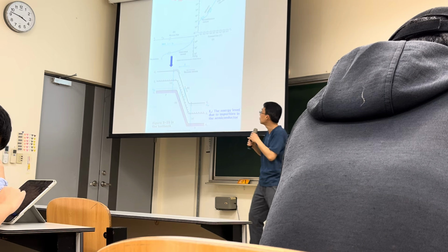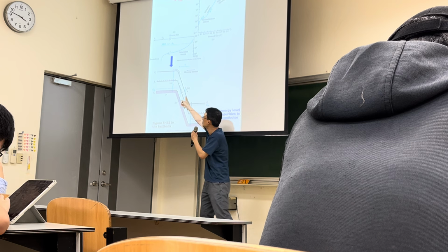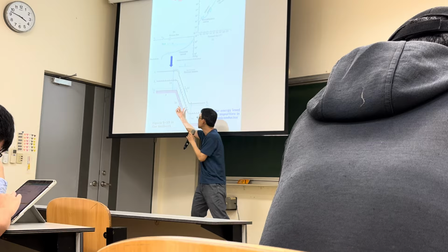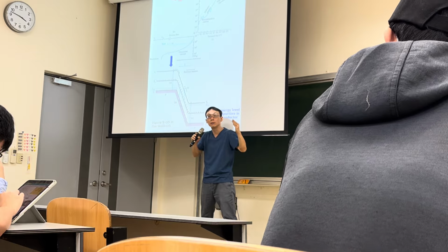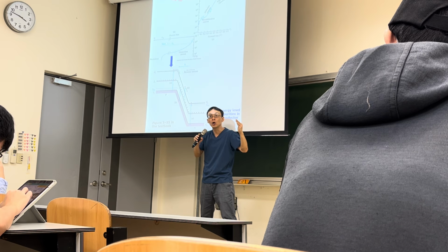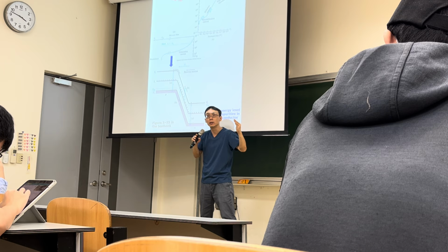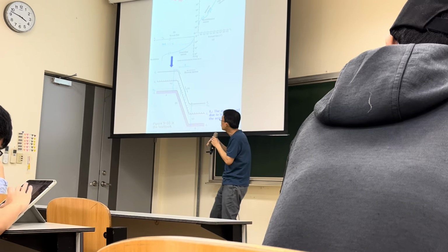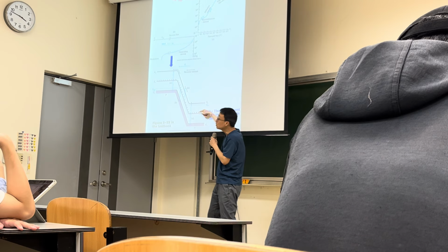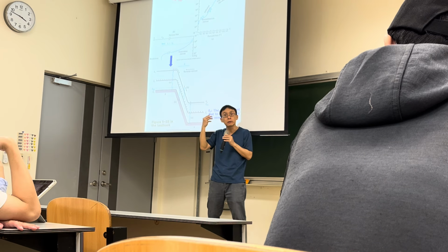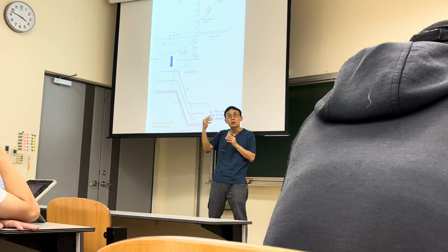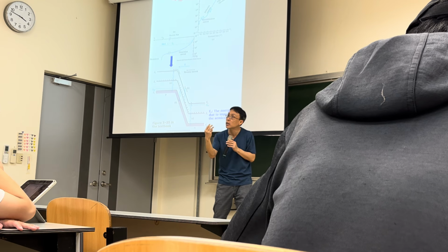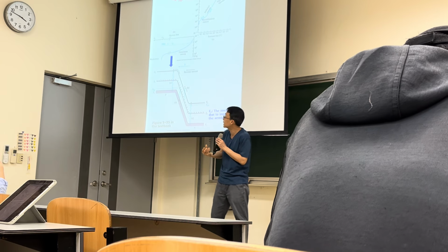If you increase the reverse bias, you are making the slope steeper and making the width of the depletion region longer, which will make it more likely for the electron in the impurity level to be excited due to impact ionization, which is the same mechanism as the avalanche breakdown.